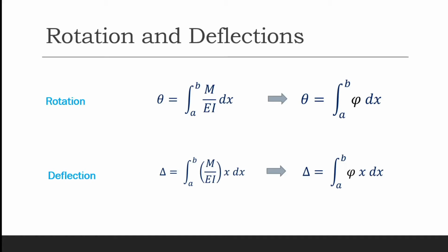Deflections, we will have a separate discussion on how to calculate using the moment curvature curve, because I think this is a very powerful tool and it can be used quite effectively to compute the deflections both for simply supported and continuous beams as well as for columns, slabs, and other members.